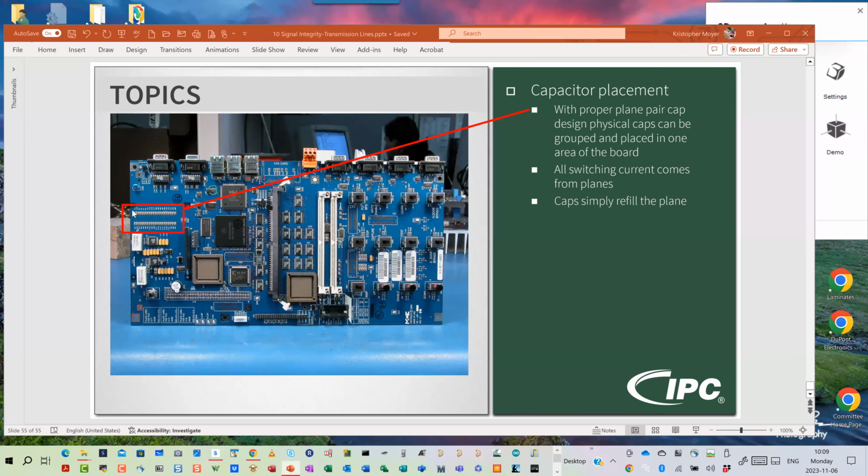half nanosecond, quarter nanosecond edge rates. Like I said, there are companies doing stuff now in the 5 nanometer, 4 nanometer, 3 nanometer where they're getting 100 picosecond edge rates. This thing, because of that L term, cannot respond that fast. So yes, you can put it there. It's still not going to do anything. It's all going to come out of that plane.